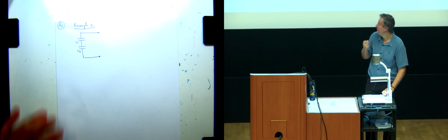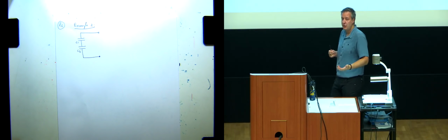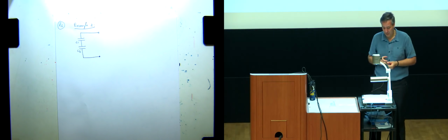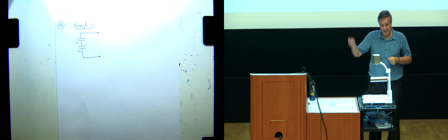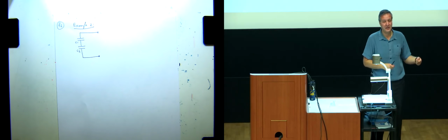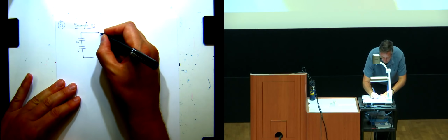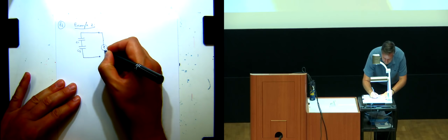And in this case, what is easier to do? Apply a voltage or current? Current, right? Why is that? Yeah, because these elements are in series. The definition of elements in series is that they get the same current through them, right? So then I don't have to solve for that current going around, right? So I'll just apply I test.